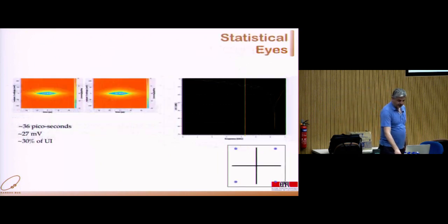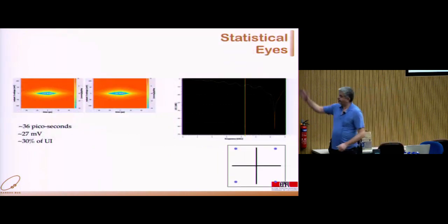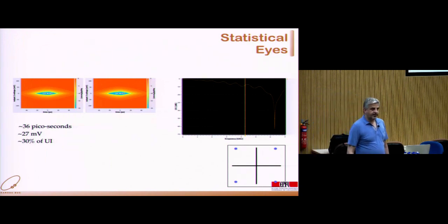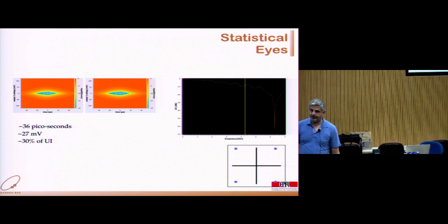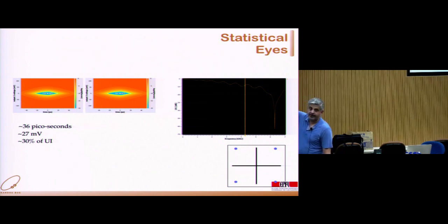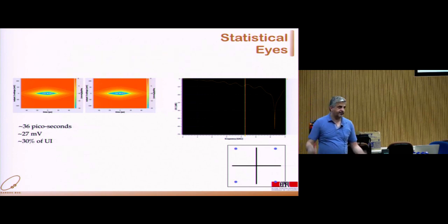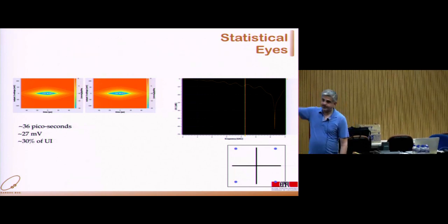This is a case of a mobile memory. And I do realize that you may not know these, what are called eye diagrams. But think of it this way. These are waveforms that you're sending over the wires, and then they're received at some point. And think of it this way: the bigger the blue part, the more resilient the system is to noise. If you sample the signals within the blue part, you're OK. Outside of the blue part is hell.